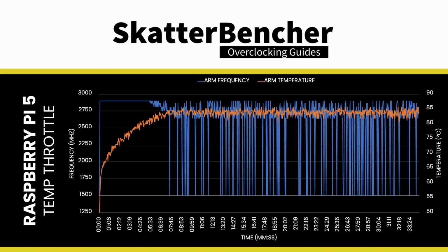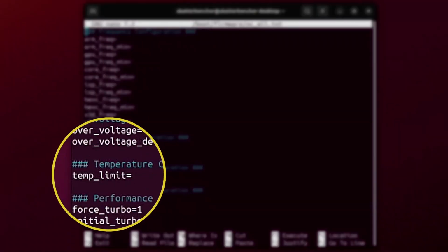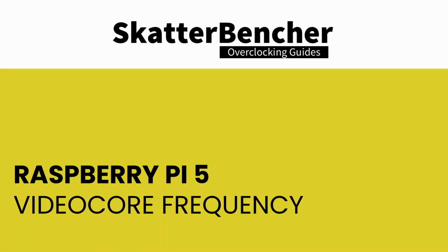However, as we continue to operate at the thermal limit, the frequency throttling becomes more severe until eventually the ARM turbo boost is disabled and the frequency drops all the way to the base clock of 1500 MHz. While there's no way to override the maximum allowed temperature, we can further restrict it by using the temp limit parameter. The VideoCore frequency is tied to a variety of IP blocks on our SoC.